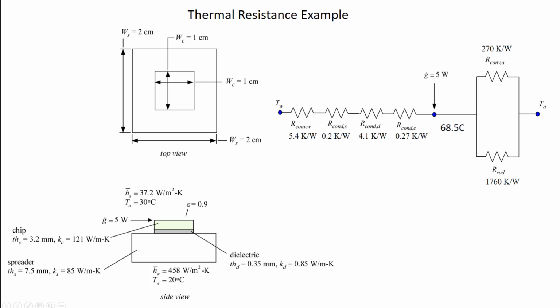And so right away, I know that this resistance here, not very important. This resistance here, at least in terms of this path, is very important. And actually, the other way you can see that is if you calculate the parallel combination of this guy and this guy, what you're going to find is that it's very close to 270. It's just a little bit smaller than 270. And again, that's because this is the important resistance associated with this path. So this path has a total resistance of 270. Let's keep that in mind. It's a little less than 270, but something like 270.